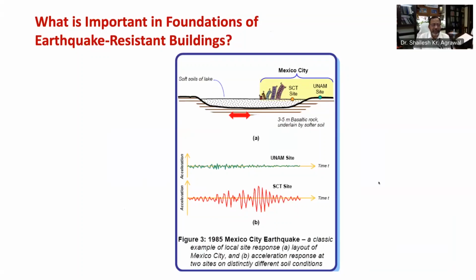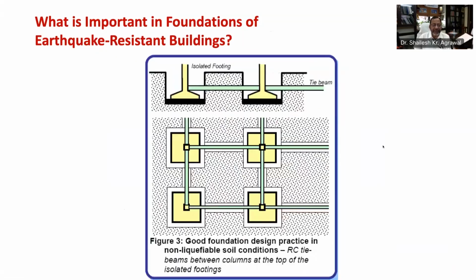Thorough geotechnical investigations at the site are a must for design projects. In addition to traditional standard and cone penetration tests, other in situ tests such as shear velocity test and pressure meter test may also be performed while designing earthquake resistant structures. Depending upon the geotechnical conditions and structural configuration and loads, a suitable type of foundation must be chosen.